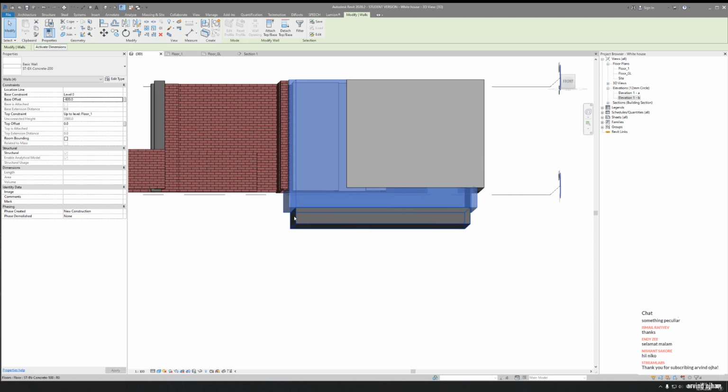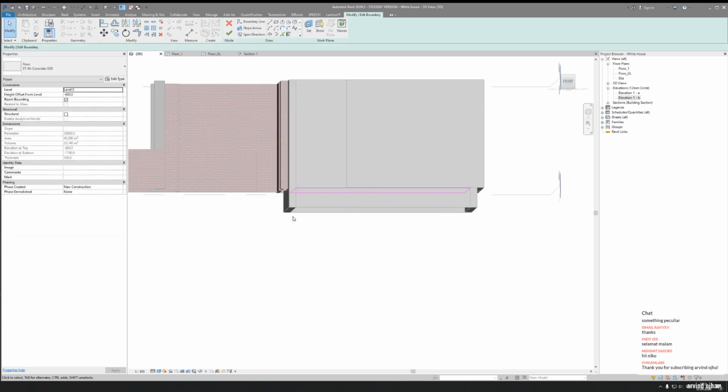Actually, this is starting from 600mm, but it's wrong, because we have the pad. So we have two ways to solve this problem. This is already construction stuff, so if some construction people are watching, please let me know and maybe you can help me, because this is done by structure engineers, not architects. So we are just following what they did. We can explode our pad and cover this gap, or we can place our walls a bit deeper. I prefer to just change this pad.